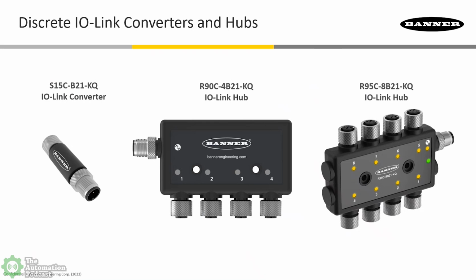Another thought I had is some of these IO cards, especially analog cards, have seen very, very long lead times. Yeah, I work with multiple vendors. I teach at the automation school, and I was actually picking up stuff on the used market because I had to do lessons and I couldn't get the new stuff. So you can avoid that if you're finding particular analog modules tough to get, by converting to IO-Link.